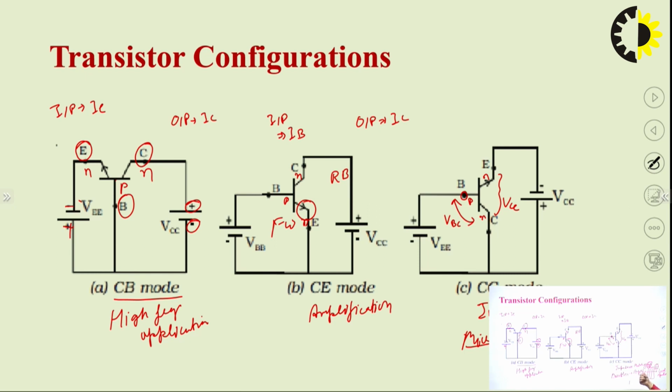So when power is transferred from amplifier to loudspeaker, it will be lost. So that's why common collector is inserted in between the amplifier and the loudspeaker, because common collector has a high input impedance and low output impedance. So high input impedance will be connected with the amplifier, and low output impedance will be connected with the loudspeaker. This is how we can explain impedance matching, that the common collector configuration is used in impedance matching.